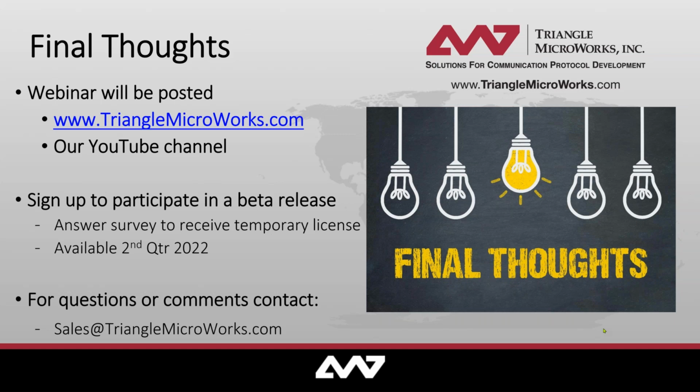Sure. First of all, on the point that DTM doesn't simulate SEL devices, we actually do regularly. Now, we don't simulate exact behavior, but in this particular case for gateway tests, you don't need behavior. We load the model of the SEL device and we simulate it from a protocol perspective, and we can send every signal in the model to the gateway. So typically, yes, we absolutely test with SEL and ABB and all kinds of other devices on both the downstream and the upstream side. We don't need to simulate the actual behavior of the device for these particular tests, because all we're doing is testing the protocol.